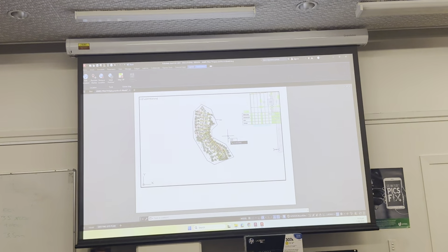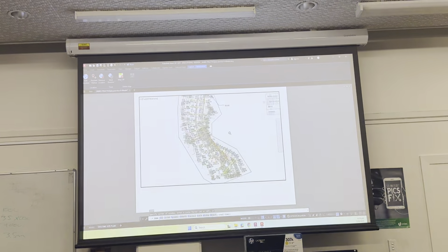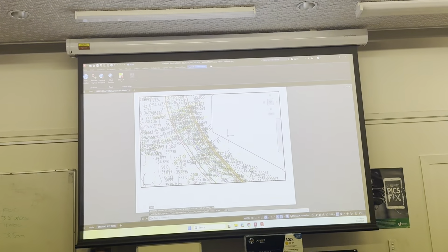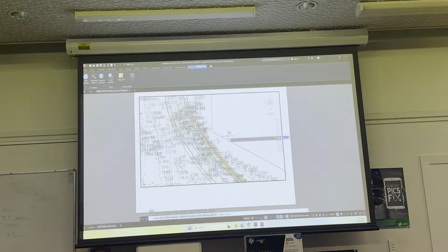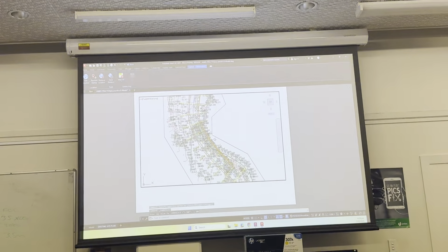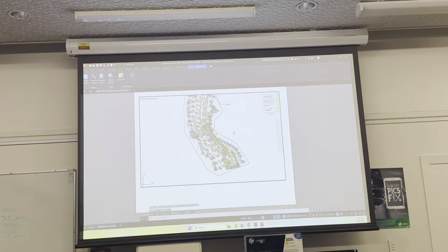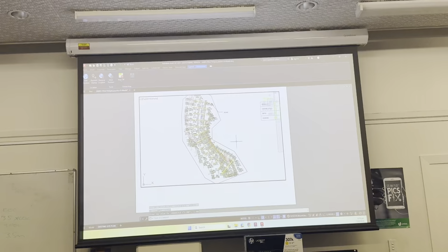So for the zoom, Z, then E, XP, 10XP. Go to layout, then Z. Then go to viewport. You type in viewport and you can change it. If it asks you for 1 to 200, obviously you choose 1 to 200. Then go single.